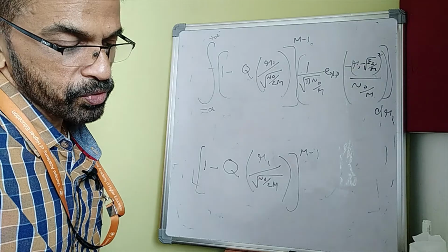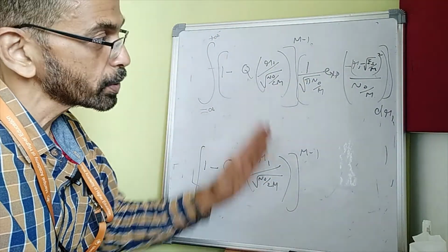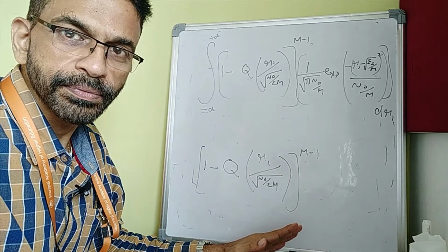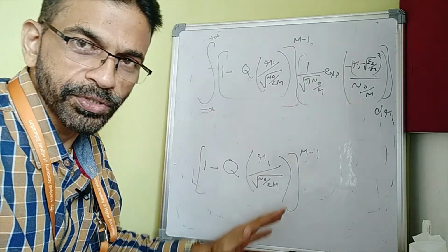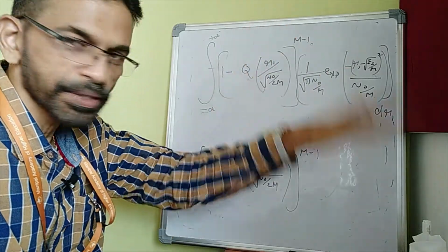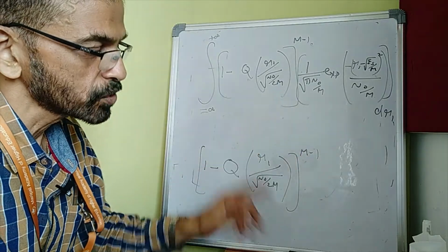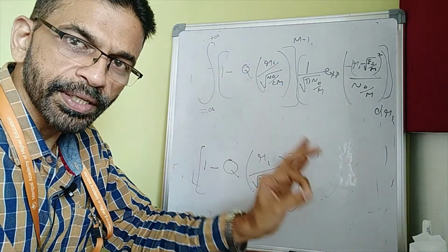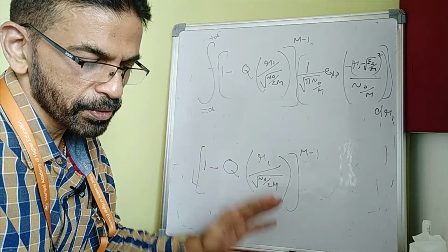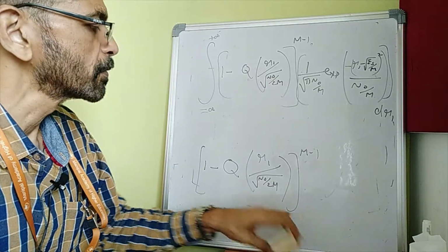And hence what happens is this is the probability that all the R's, or this is the probability that R1 will be the largest, because all the other R's are less than R1. This is the probability that R1 will be the largest, and this is the probability that the symbol corresponding to S0T is being detected correctly by the receiver, or the receiver declares that S0T is the transmitted signal.